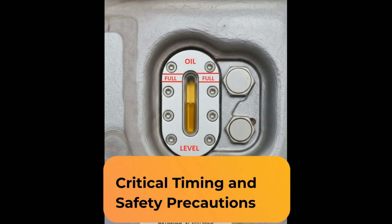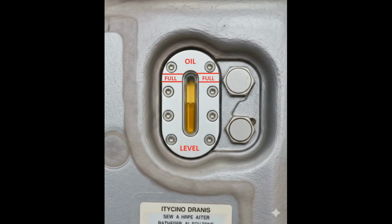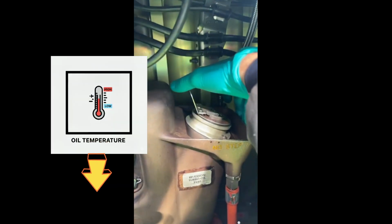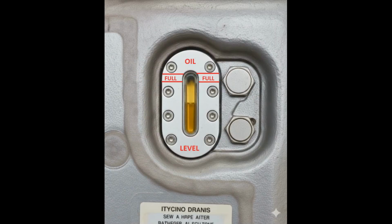Critical timing and safety precautions. Verification window. The engine oil level check must be performed within 30 minutes after engine shutdown. If this 30-minute window is exceeded, the oil temperature drops, leading to a change in oil volume, contraction. This results in an inaccurate reading on the sight gauge.